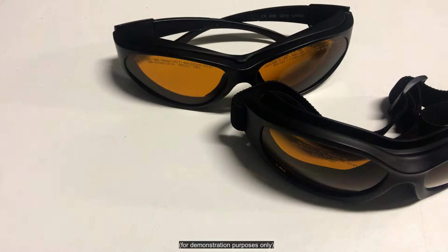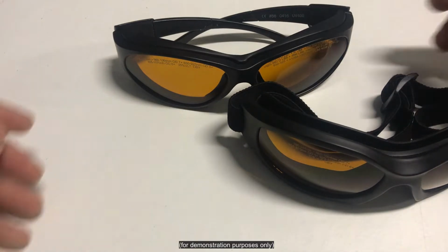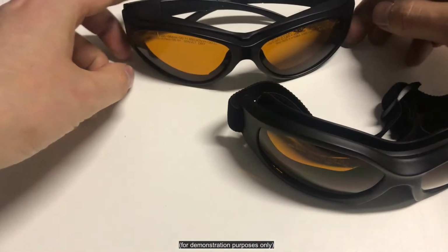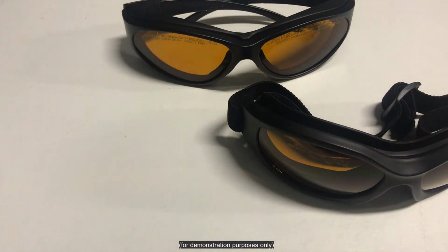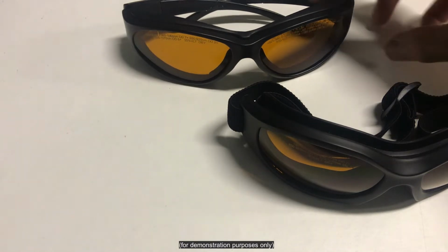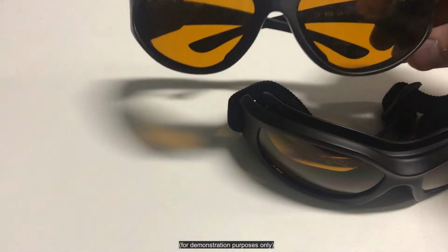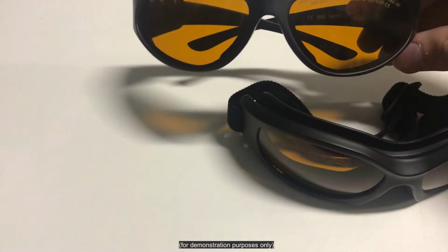Next you'll have some laser safety goggles, and these particular goggles will be rated to the wavelength of laser light that you use. The type of laser that we use is a neodymium YAG laser, which inside the cavities emits in the infrared, but when that's joined and comes out of the laser itself, what we see is a green light, which is 532 nanometers. So these goggles are tuned to provide protection and filtering to a certain standard for 532.